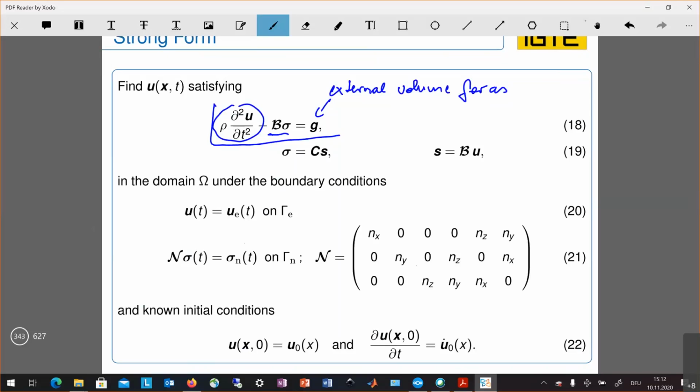In addition, we have our constitutive equation. The constitutive equation giving us the relation between stress and strain by our material tensor C, which we have seen that for the isotropic case, it is just computed out the entries by the mechanical modulus E and the Poisson ratio nu. And importantly, that we end up at the partial differential equation for the mechanical displacement U. We have the relation between the strain and strain components and the mechanical displacement U by the same differential operator B here.